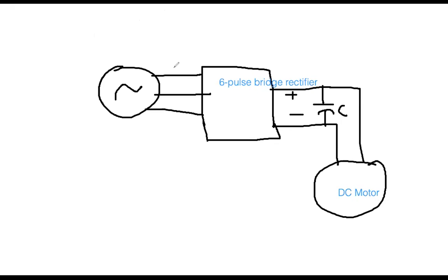Because this side is AC, for example, this is A phase, this is B phase, this is C phase. The generator rating was mentioned as 11 kV, and it has a 60 Hertz system. Those two pieces of information were given. And this is 6-pulse, and it also says full conduction. Full conduction means the firing angle alpha is 0 degree.